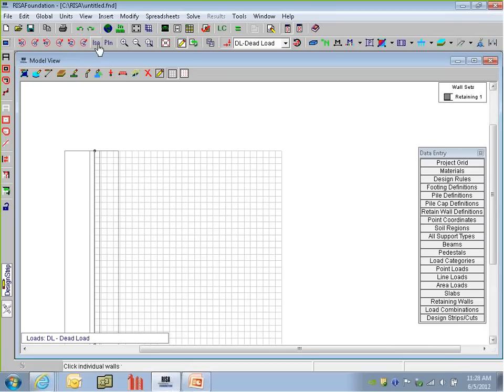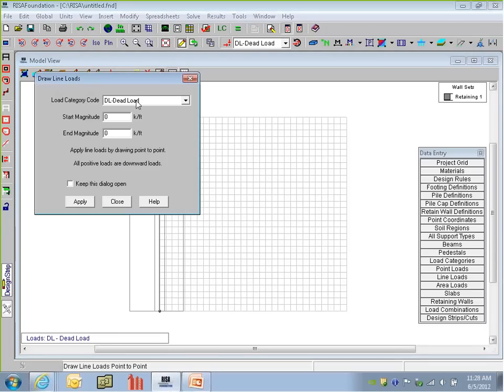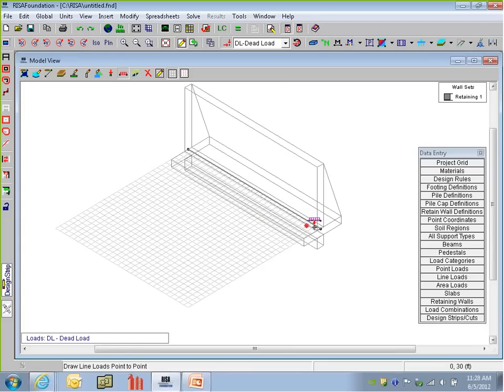So I'm going to look at this back in plan view, and I can do a lot of different things with modeling for the loads. The one load I want to do is define maybe some dead load. So I'm going to go to here and apply some dead load, and I'm just going to put some fictitious loads on here, maybe 1 kip per running foot, and I'm going to just draw that. Now when I'm drawing it, I want to make sure I'm drawing this on the wall. And just like we saw when I showed this slide, I'm going to draw it from the center line of that point to the other center line of the other edge of that wall. I can go shorter, but I'm going to go the entire thing.